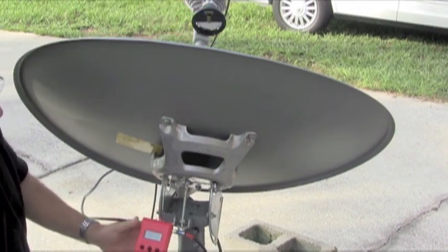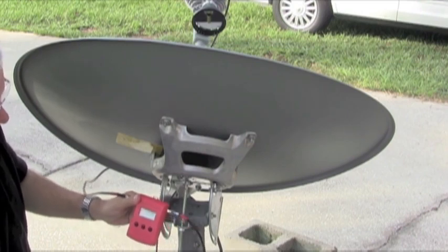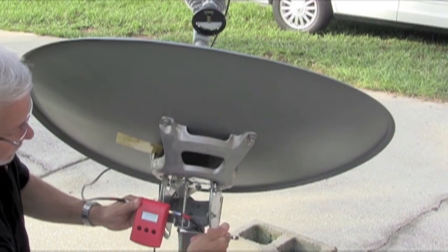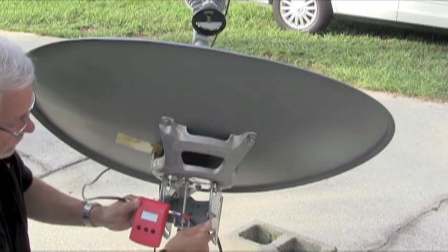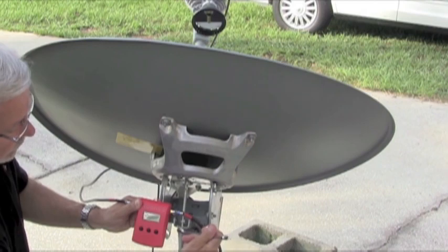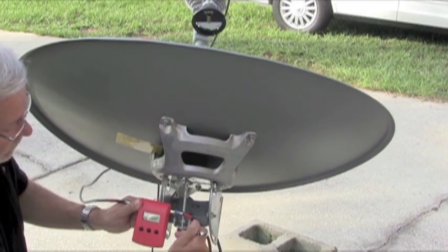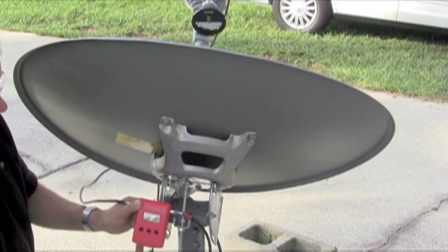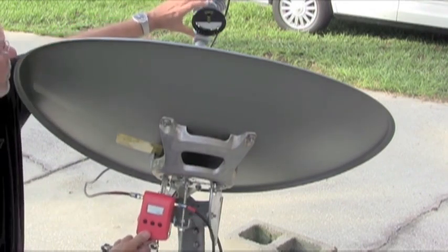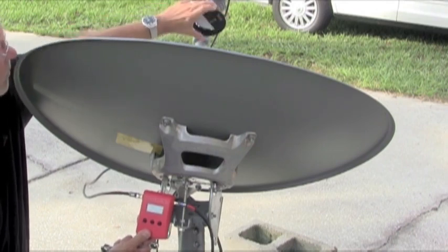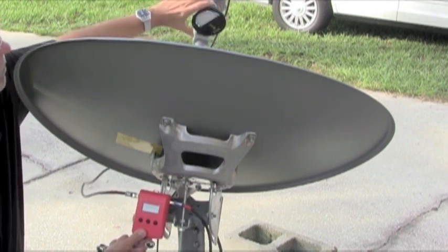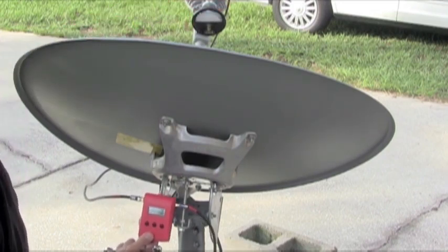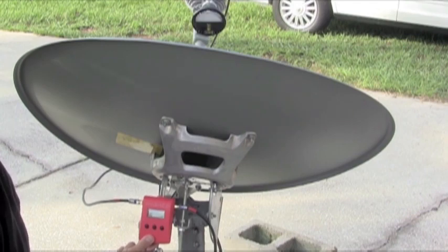So that now shows 102. So we have about a 7 to 8 point difference, 102, 103. So we're going to make a small adjustment to elevation to bring that number down and meet that value in the middle. And we'll go ahead and check it 180 degrees again on elevation to make sure that that adjustment brought it within 5. And it does look like, yes, we got it within just a couple points.